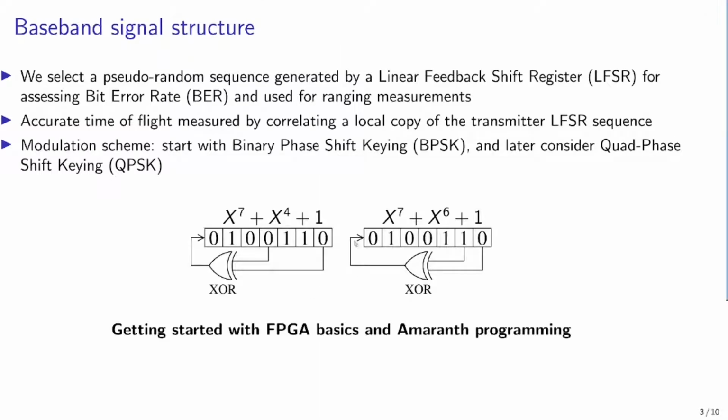So in this case, for example, you would say that here you have 2^0, 2^1, 2^2, 3, 4, 5, and 6. That's the 7-bit long register. And here, 2^3 over here would be 8. 2^2 over here would be 4, 0, 1, 2. And so this means that you will represent this polynomial as hexadecimal 48. Similarly, here you would have 2^3, 8 here, 2^0, 2^1, 2^2. So here we have 2 plus 4 equals 6. So this would be 0x60 if we represent the polynomial.